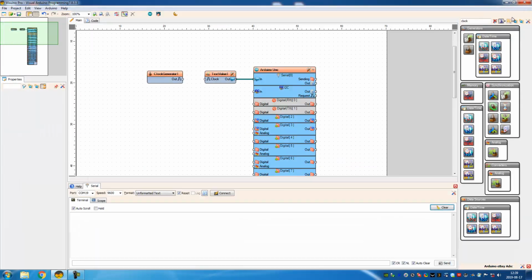Okay, it's gonna be sending this value only once. So when I connect, it's gonna show up once and no more. Okay, this might not be a problem as you see, but some cards, when you connect it to the serial terminal, it's not gonna be resetting the board. It's just gonna connect it to it, and then when it connects without having to reset the board, you're not gonna see any test value.